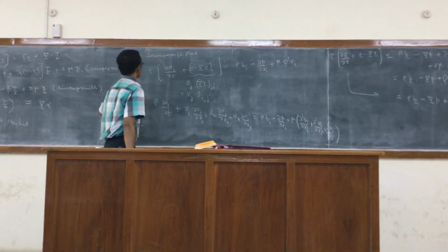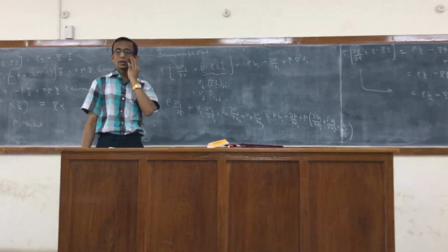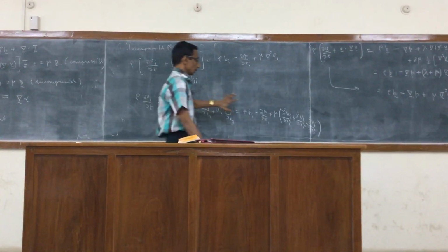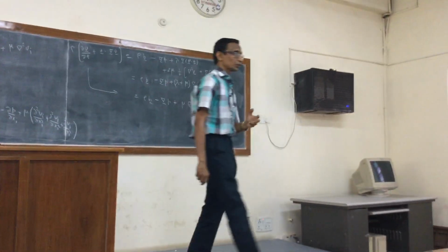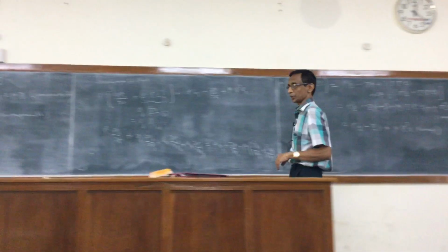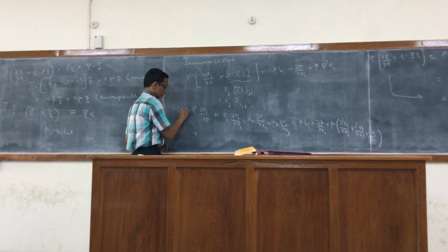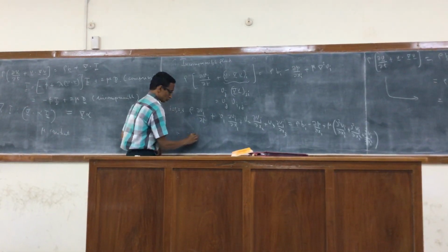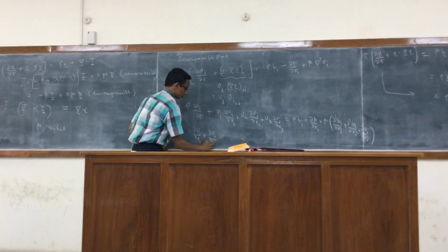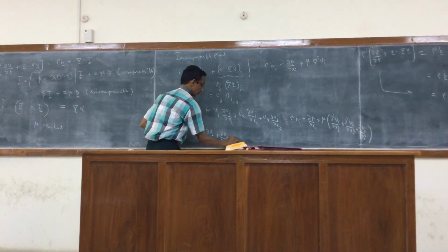this has to be solved for the incompressible fluid in combination with the continuity equation, because there are three variables here, V1, V2 and V3, and also the pressure. We need another equation, and that will be given by i equal to 1 to 3 plus the continuity equation, which would be simply dV1 by dx1 plus dV2 by dx2 plus dV3 by dx3 equal to 0.